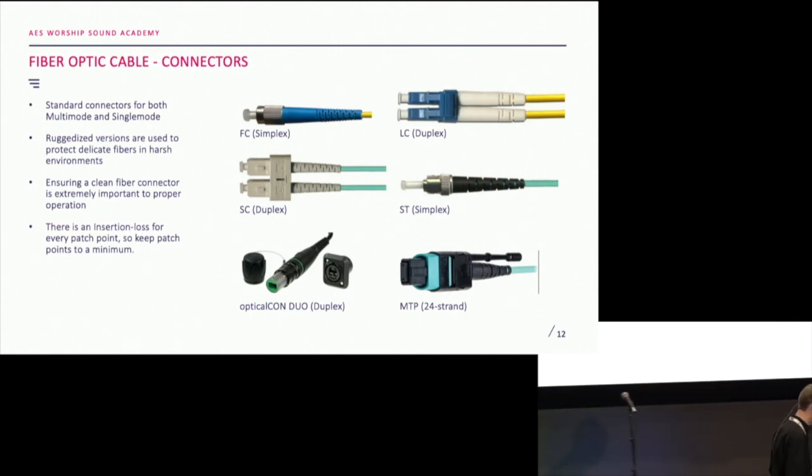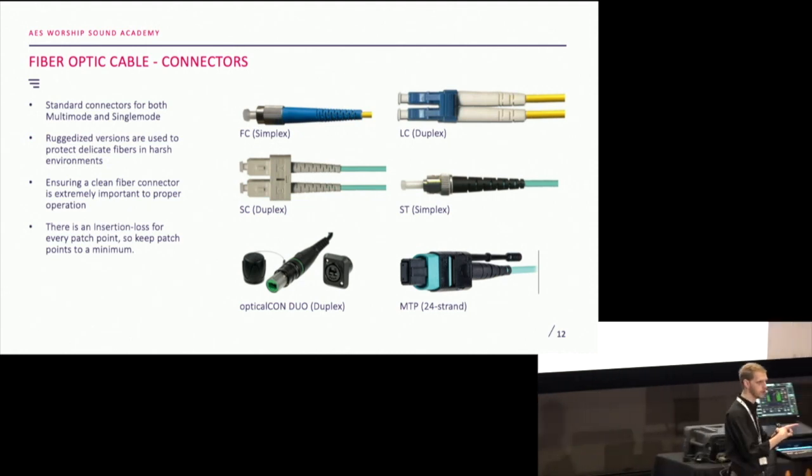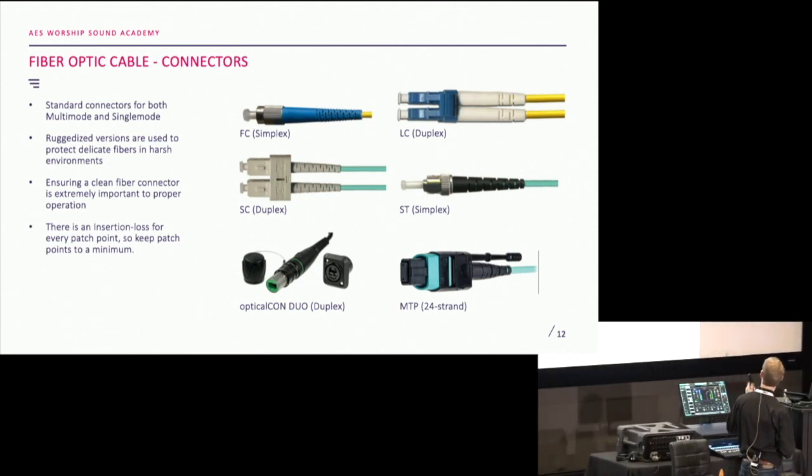And when we talk about Ethernet and networking, we've got to have a transmit, but we also need to receive. A lot of times when you get into fiber, you need the duplex, meaning you've got a transmit and a receive side. And so you can see I've shown the duplex for both the LC and the SC, so you kind of get an idea, okay, it's a 2-way communication that's always happening. With our copper cable, our Cat5 cable, there are 8 conductors in there. Those conductors are doing the back and forth for us, and all we know is we just plug it in and it works, right?